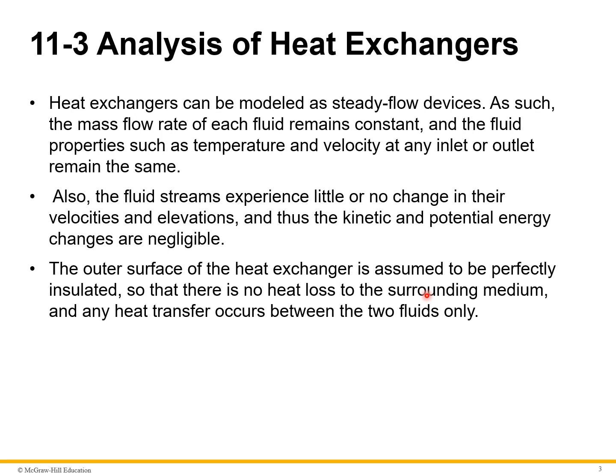Heat exchangers can be modeled as steady flow devices. As such, the mass flow of each fluid remains constant, and the fluid properties such as temperature and velocity at any outlet or inlet remain the same. Also, the fluid streams experience little or no change in their velocities and elevations. Thus, the kinetic energy and potential energy changes are negligible. The outer surface of heat exchangers is assumed to be perfectly insulated, so there is no heat loss to the surrounding medium, and any heat transfer occurs between the two fluids only.